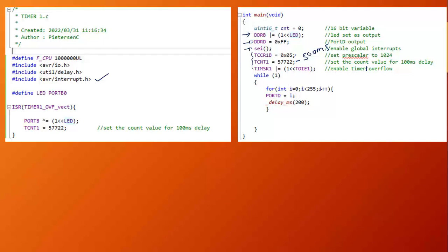And here you can see I just have a for loop, and port D will display the count at 200 millisecond intervals. But now remember, when it simulates, it looks a bit off, but that's because timing in Proteus isn't necessarily all that well set up, so you sort of just have to use your imagination. But from a technical point of view, we know we are correct.